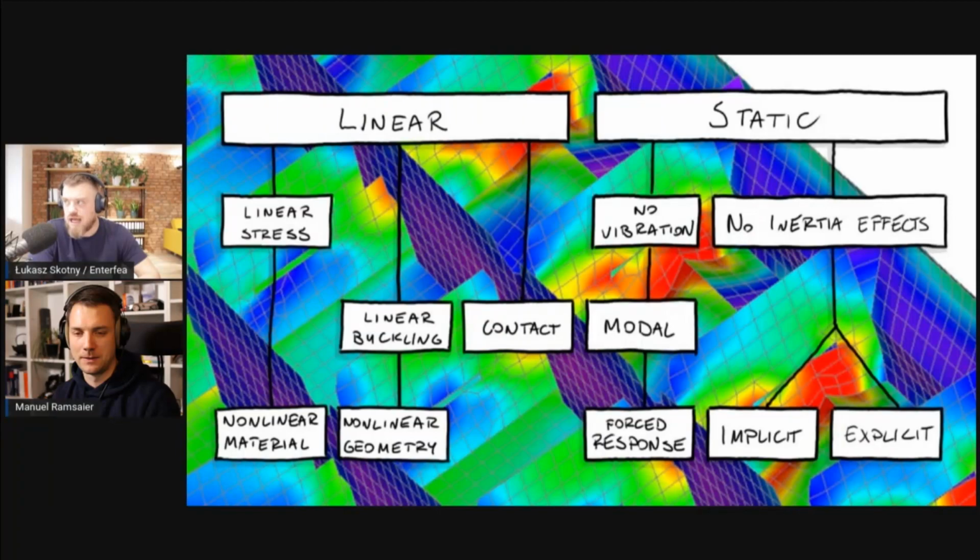And I feel that this analysis, sadly, is just as overused as linear stress. I mean, if you would be solving simple beam structures and you have buckling, maybe lateral torsional buckling, and you have 7 degrees of freedom, or you model things with plates, if this would be like beams we're talking about, those would actually behave decently with linear buckling. You could use it for cranes, for example. The buckling value you will get for those is reasonable. But that's not because linear buckling is so great. That's because beams are very nicely codified.